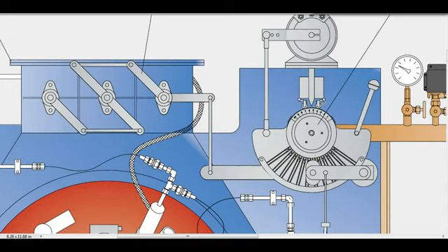Let's say as the link moves up, the cam moves this way and the link opens up more air, which means the linkages move in this direction, thus becoming in this fashion and allowing more air to match the amount of fuel. But what is behind this compound regulator?